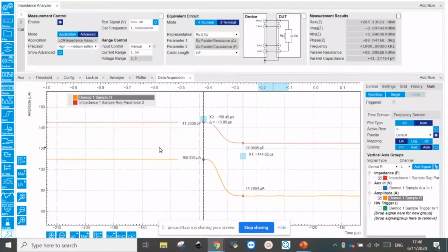Now let's move to another question from Antonio. Can you connect the instrument to a probe station for on-wafer transient time test? Yes, absolutely. Typically, DLTS would be done in a cryostat, but the MFIA can, of course, be connected to a room temperature probe station. It would be recommended to work with passive probes, and you would need either 2 cables or 4 cables, depending on whether you're looking at 4-terminal or 2-terminal measurements. But the functionality should be relatively plug and play.